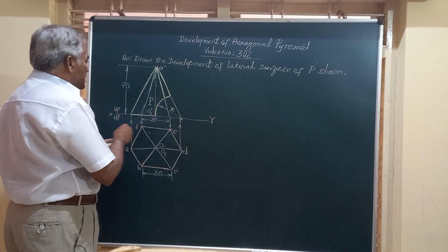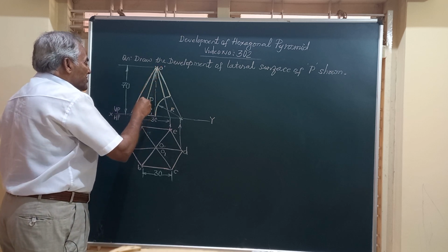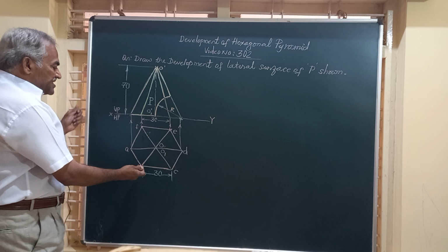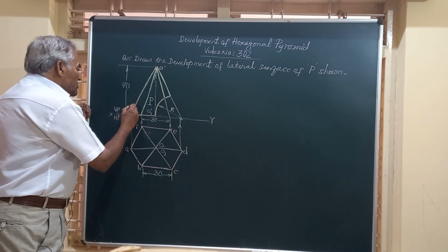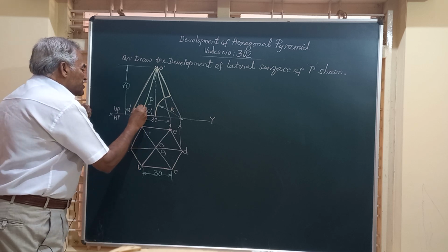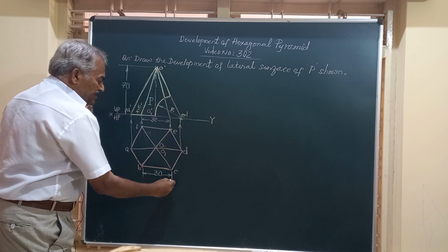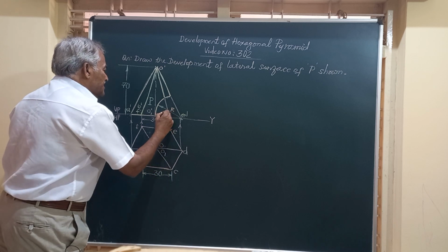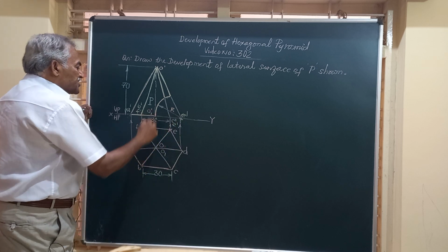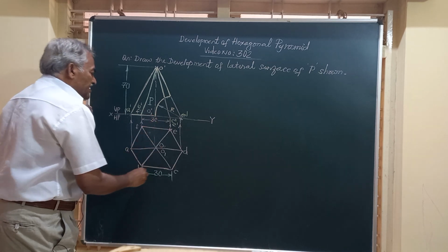These are the slant edges in the front view. We have 6 slant edges. Friends, let us transfer all these points to the front view. So this becomes A dash. B and F will come together, so we'll say B dash, F dash. This is E dash at the end. Then C and E will come together, C dash, E dash. And the center one, we are not sure about anything, so we'll take it up later.